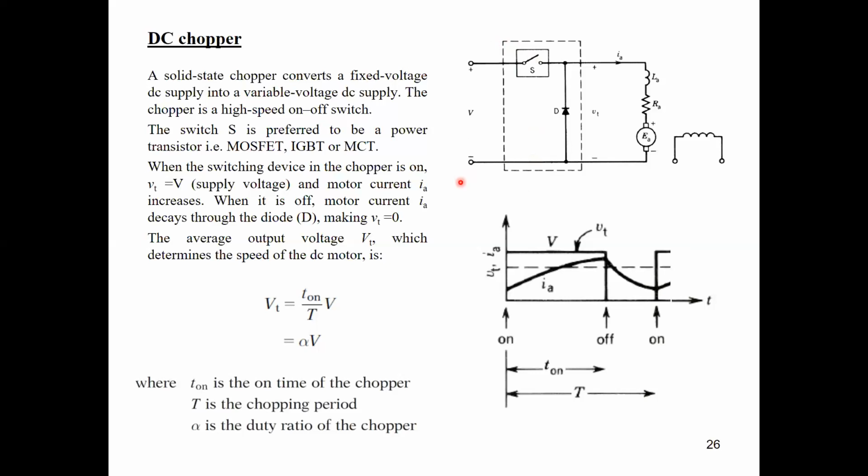So as we can see here, the voltage and the current polarity will be positive all of the time, which means this circuit can be used only for motoring modes. However, if we need reverse voltage or reverse current, or both voltage and current negative, we have to use other circuits, and we are going to describe them later, inshallah.